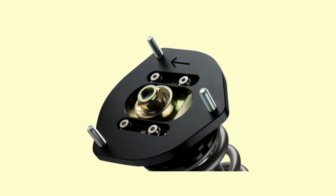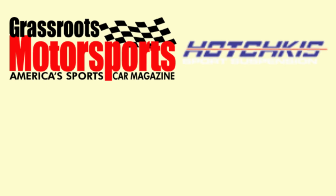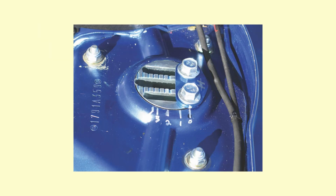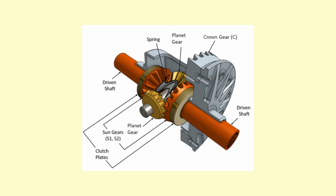A good example is where in 2007, Grassroots Motorsport, in a collaboration with Hotchkiss Tuning, worked on a 2005 Mini Cooper to test the true difference that negative camber makes to one's track times at the Streets of Willow Springs, adding a slew of mods including competition camber plates. Fitted with negative 3 degrees of camber, the Mini was 1.2 seconds faster than when it was fitted with negative 1 degree of camber. Lastly, consider installing a limited slip differential in the front.